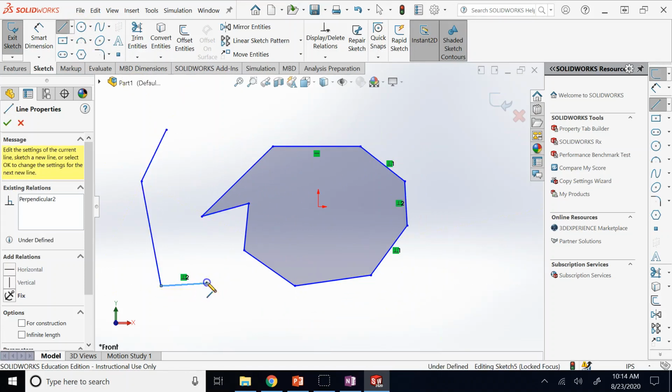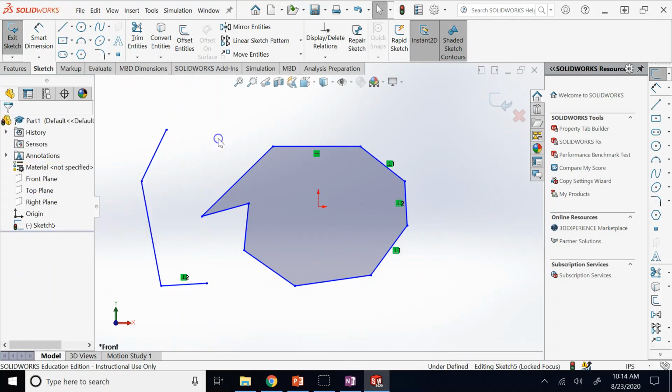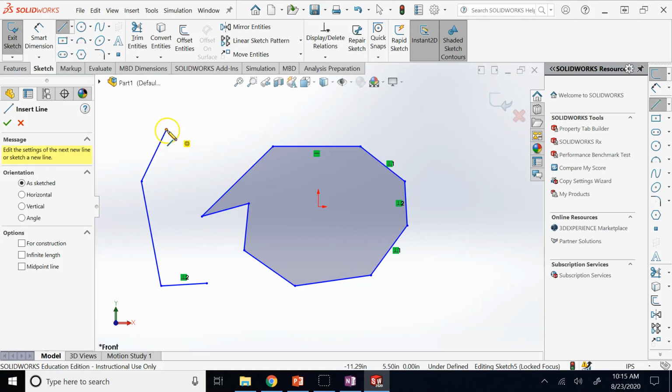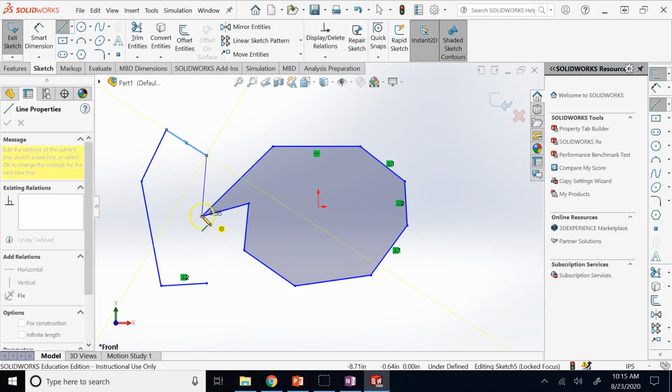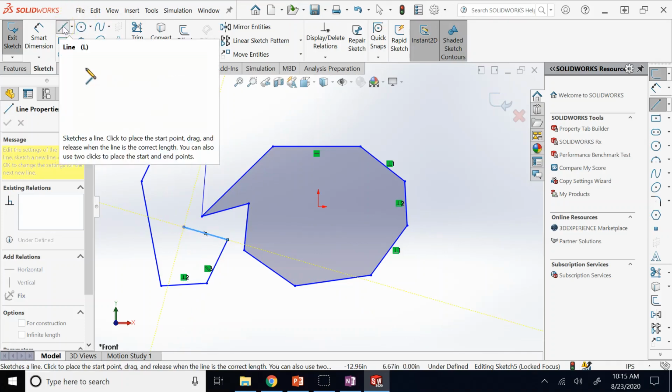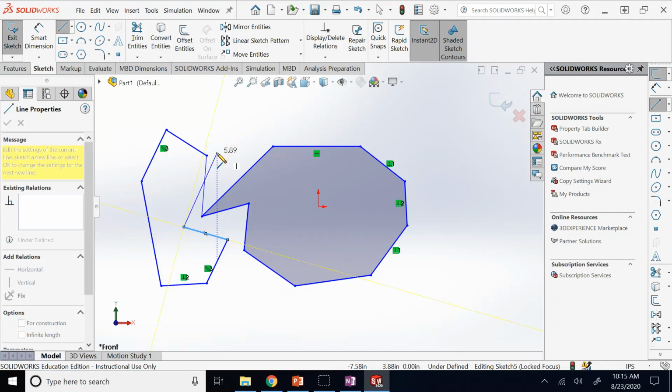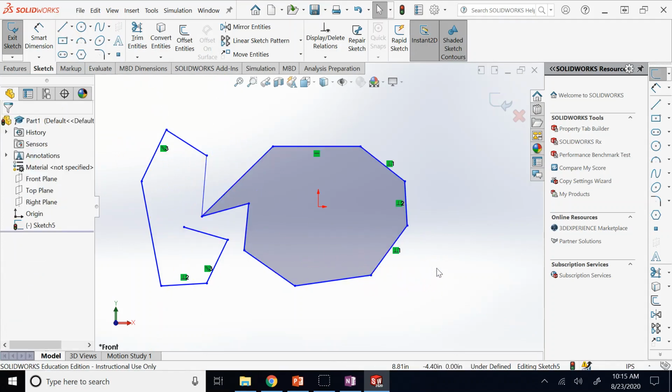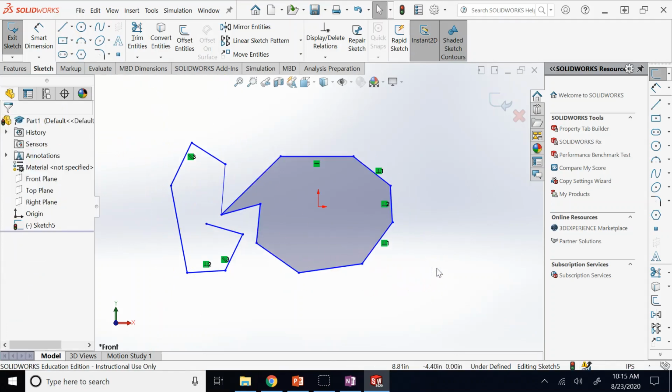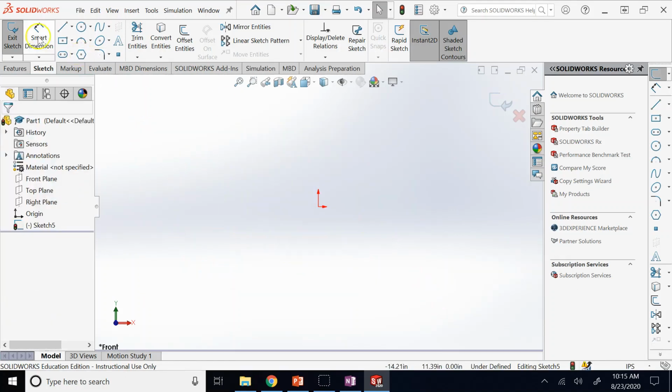You can draw more. Now, if at any point you are done, you either click here and turn it off, or, if I want to turn it off here, as I said, either you click on the command or you use escape from the keyboard, okay? That will shut the command off too, okay? So that is a very useful thing, escape from the keyboard. So this is the command line, very obvious. Now underneath that, you have center line and midpoint line.